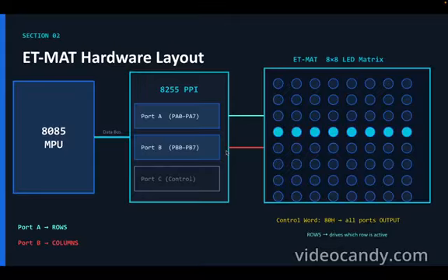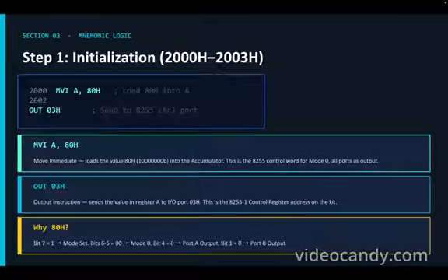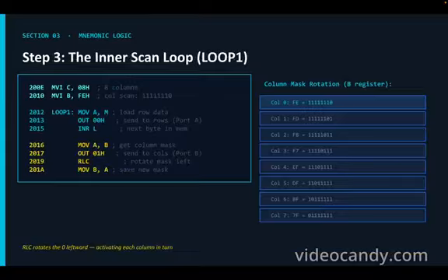If I do the experiment, you can see all the columns, whatever data you have, all 64 LEDs responding simultaneously. That's because of the speed at which this is being carried out. I will get into that soon as well, but first let's understand this part. So we are doing rotate mask left, which is rotating the value so that the next column can activate after that.